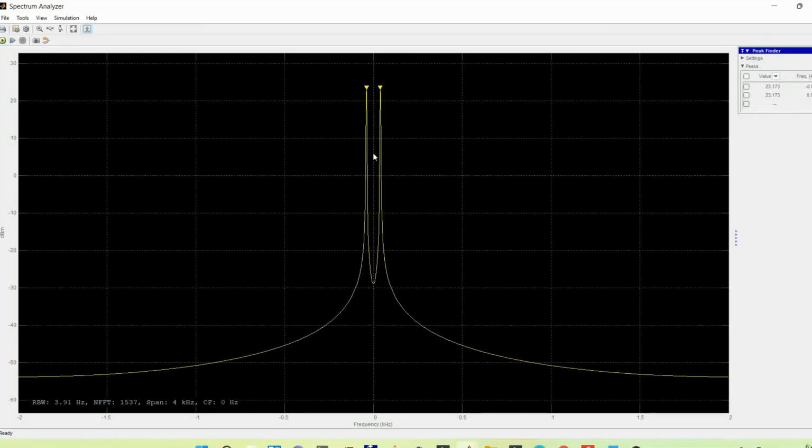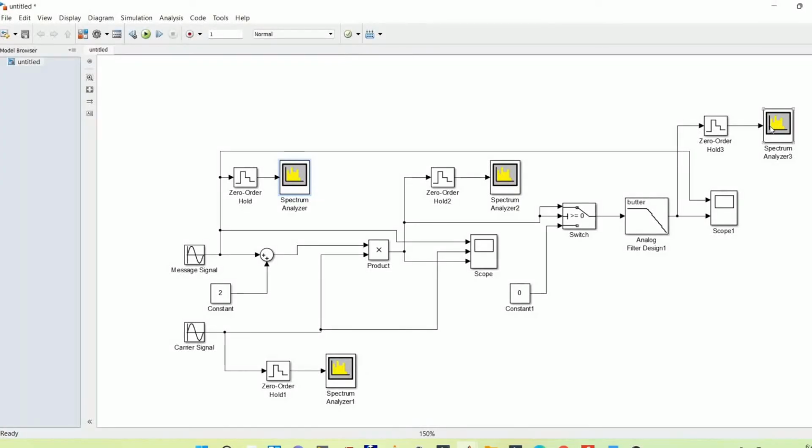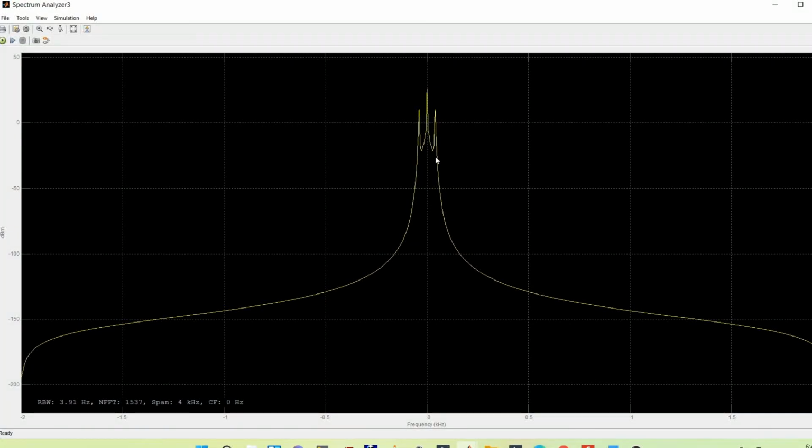You can see here positive frequency 40 hertz, negative minus 40 hertz, but the DC level was 0. At DC voltage it was a very small value, whereas here we are getting a DC voltage which we can remove in further processing. Okay, but we have successfully demodulated, that is our spectrum has been shifted from 1.5k to around 0, which is 40 Hz and minus 40 Hz, the baseband region.